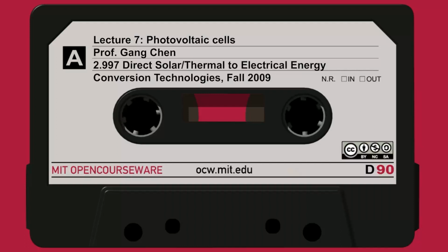I didn't write the equation later, but it's copied from Henry's paper. And this is the solid angular integration. So that's essentially the photon density of states inside the crystal. Photon density of states. So it's the Fermi-Dirac, quasi-Einstein statistics integrated with the quantum density of states. So this is the spontaneous emission due to the current that can be created at arbitrary voltage.